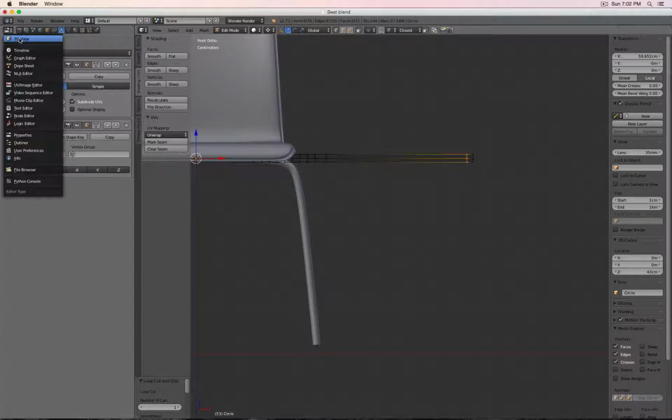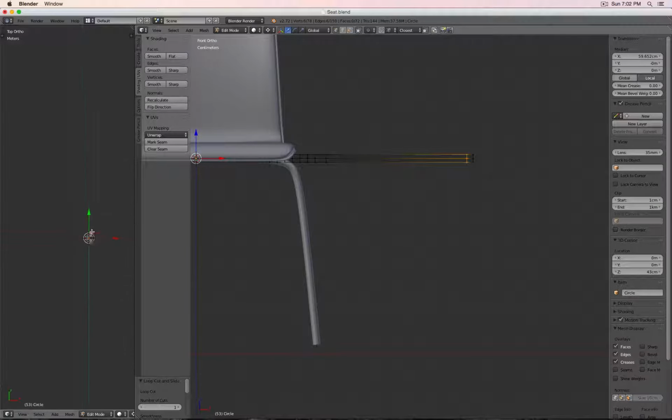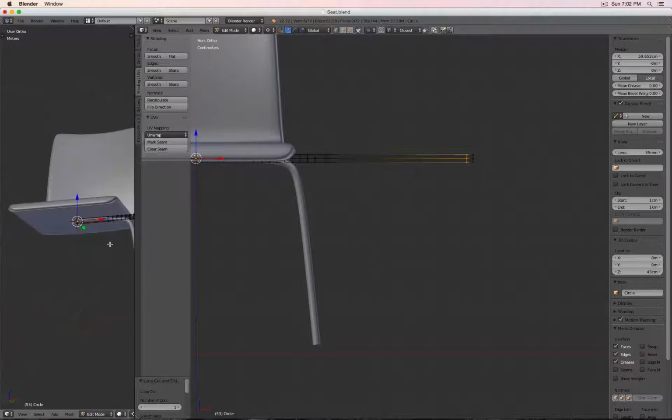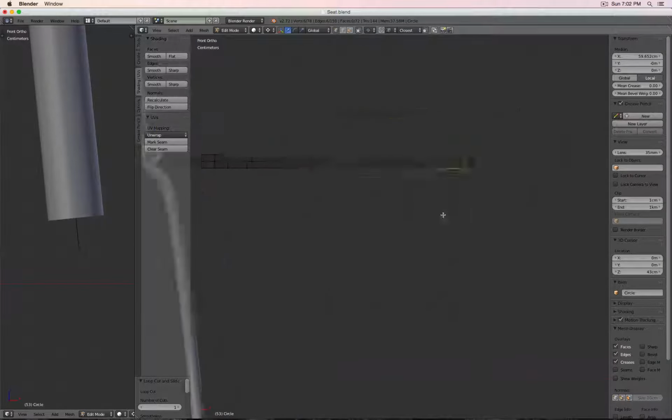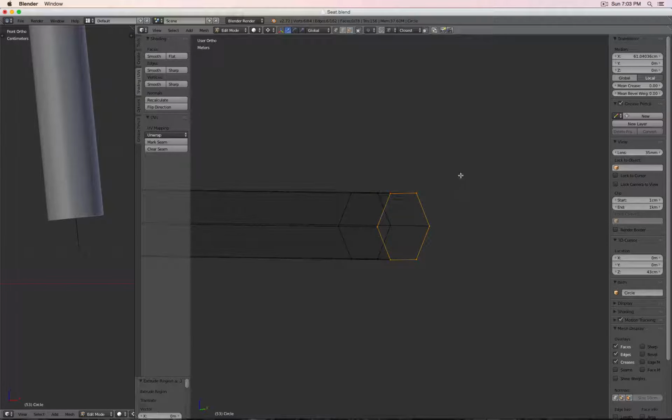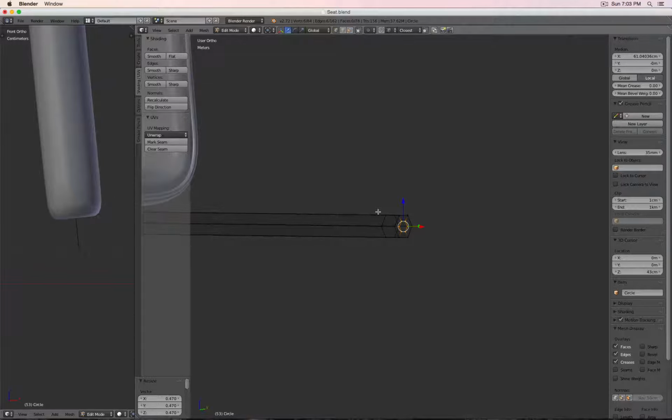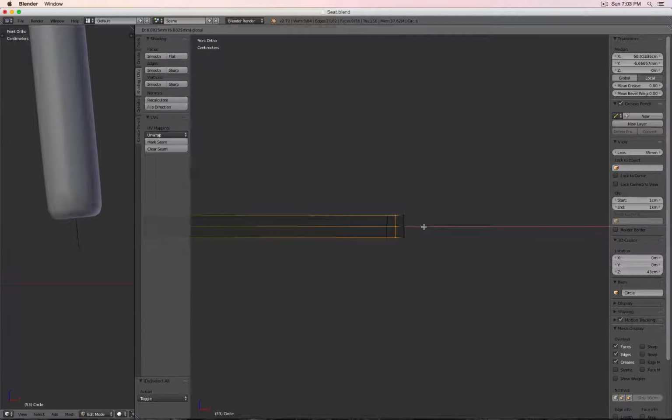So right now, for example, I go to another 3D view here, and the main reason for that is, for example, I can see how this part looks while working on this area here, and I extrude it, went to bounding box, scale it down, maybe move this one over there.